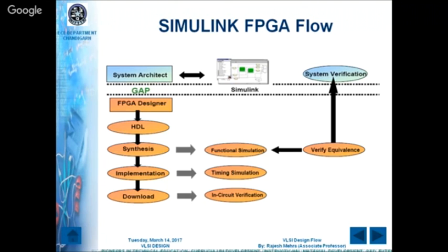So you have to perform that, and then the final step will be again your bit file generation, and that bit file will be used to check the hardware implementation of your design. So in this way we can say that we can use System Generator or Xilinx DSP to bridge the gap between your MATLAB environment and your ISE environment.